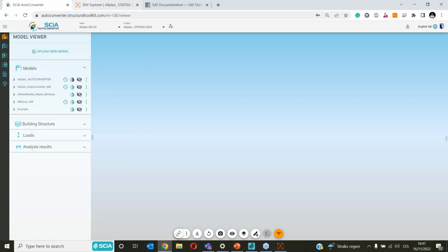In case we all in our workflows are working on BIM Plus, then most likely an issue will be created on BIM Plus that will be assigned to me, and I can check what was actually changed on the model already on BIM Plus. In case I am only working alone, then I can use upload revision in here.